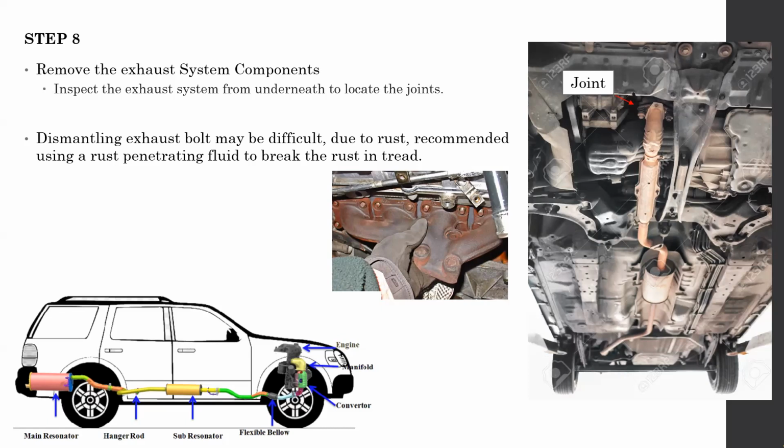But manufacturers like WD-40 make a specific rust penetration fluid to tackle such bolts. So you can spray it, leave it for a few minutes, then try dismantling it. Most of the time they come out. If it is not coming out, then you have to cut it and take it out and rethread it, then fix it back. That's the only solution afterwards.